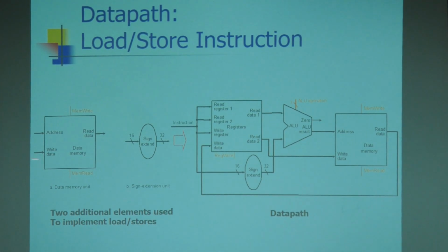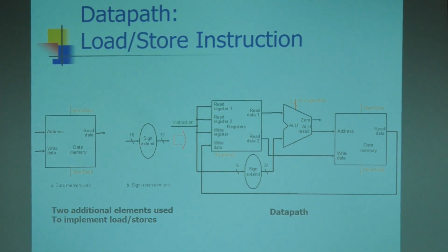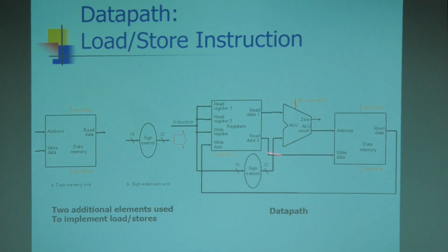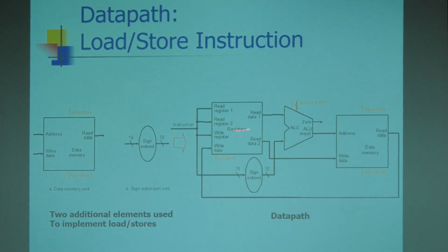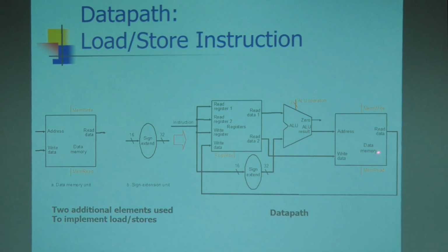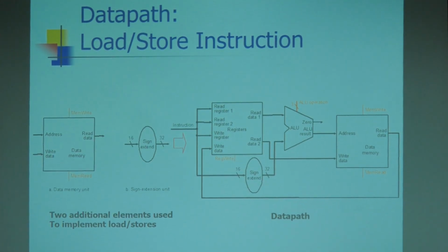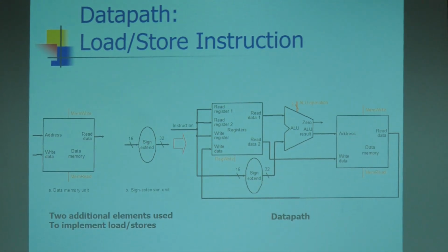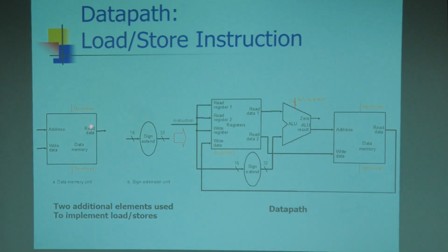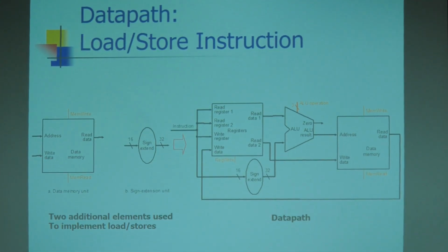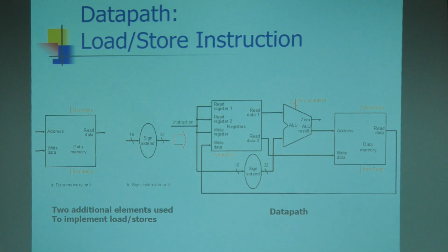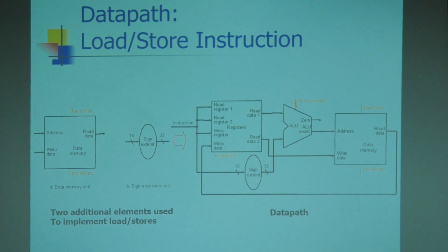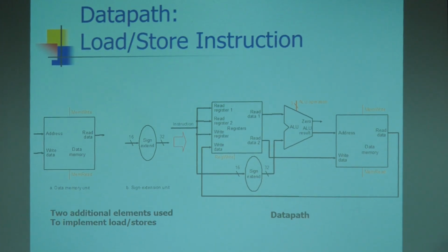Earlier it was the instruction memory, where the program is stored, and data is going to be stored in the data memory. So the data memory component is required. We are going to add the data memory component to the register file and ALU. This is the data memory unit. The data memory has the memory address, the read data or write data, 2 read ports and 1 write port. How to represent the memory?